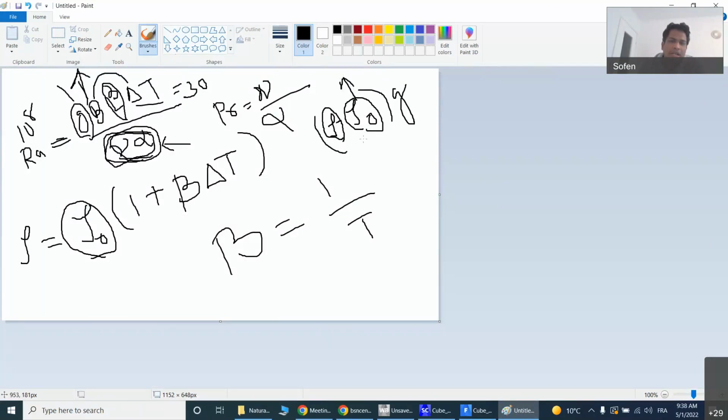This means, as per the approximation, when you are solving the Navier-Stokes equation, rho times the substantial derivative of u by dt equals a set of terms on the right-hand side. It is assumed that the density is not varying on the left side in the Boussinesq approximation. So that's why it is rho 0 here, right? Whatever the density variation, it occurs only in the buoyancy term, not in other places.